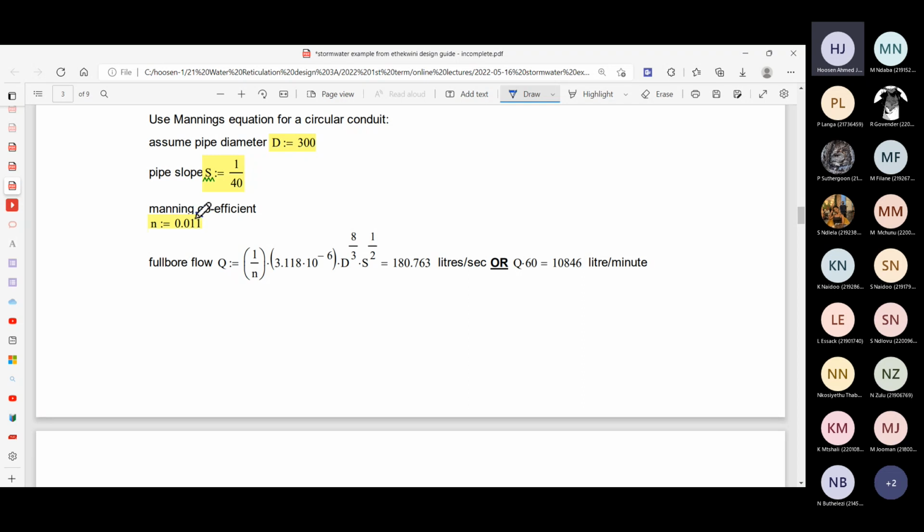I'm working here with the 0.011. That's for the new pipe. And then the full bore. Okay, now in stormwater, it's with the stormwater design pipe. Remember, the pipe dries out, right? When in between events, the whole of most of winter, there's no rain, the pipe will be dry. So you're not going to get that same, what they call it, like not scum, but that slime buildup on the pipe, like what you get on a sewer pipe.